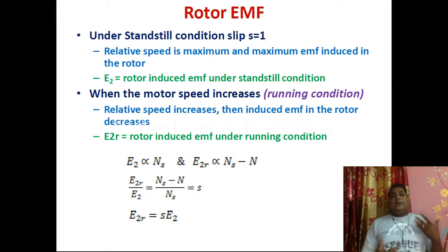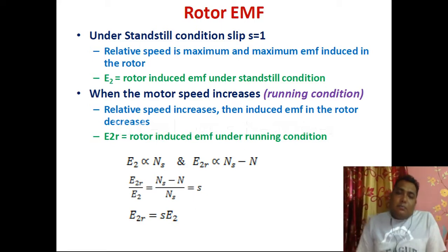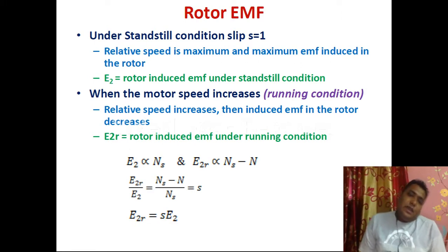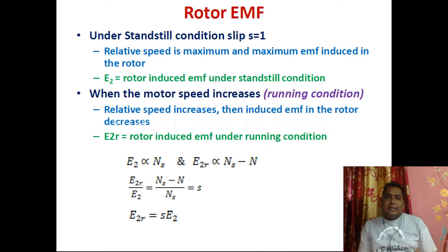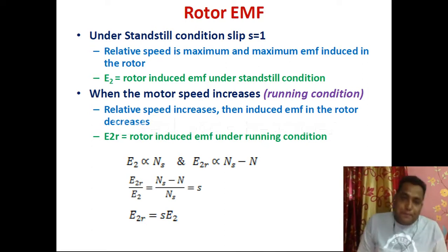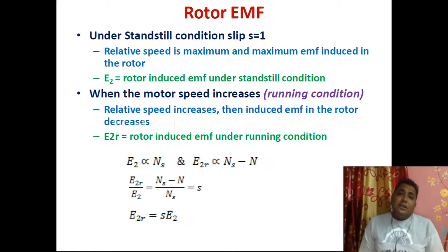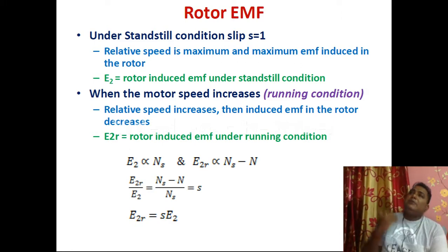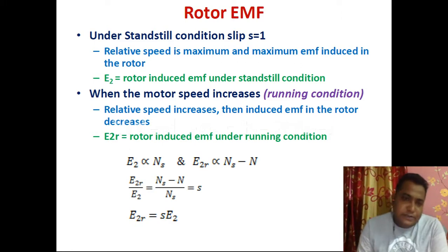That means whatever EMF is induced in the rotor is equal to the EMF induced at standstill condition multiplied by slip. So we can understand the importance of slip. For calculating each thing we need the slip. For calculating the frequency we need slip. For calculating the EMF we need slip. So it is a very important term, using which we can solve different parameters and understand different things in the case of a three-phase induction motor.